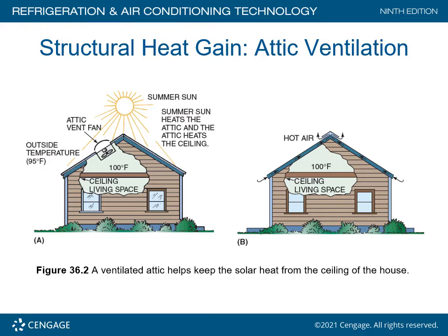That's another process. But what I said earlier really applies here. On new construction, or if you're going to do a re-roof, one of the things I recommend doing now is tearing off the wood sub-base on the structure and installing this plywood with the foil face. By installing that with the foil face on the attic side, you repel the heat back outside and it never penetrates inside. And I can tell you right now, it makes your attic probably a minimum 20 degrees cooler than with the old type of construction.